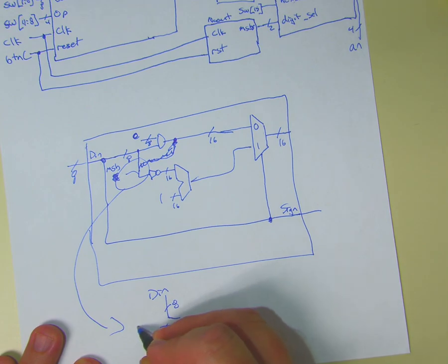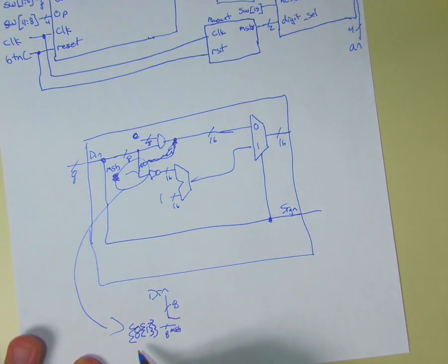And the easiest way to do that is 8, 1, which means 8 ones repeated. And this is another one of those. If you remember, curly brackets extend things. Comma lets you append things. If you want to do something multiple times, you put the number of times you want it done before the curly bracket, and that repeats them.